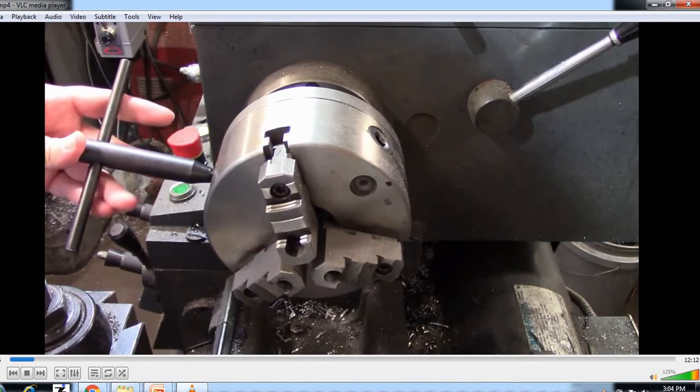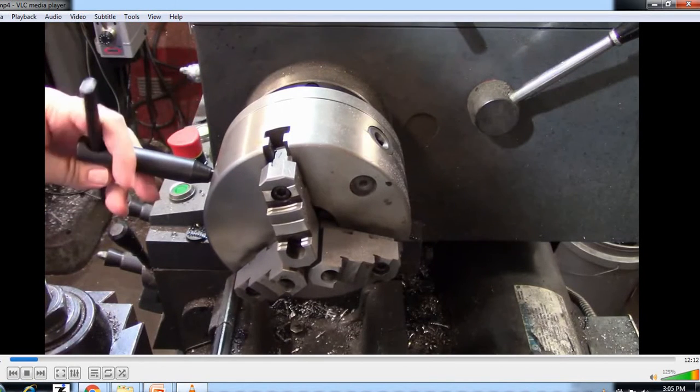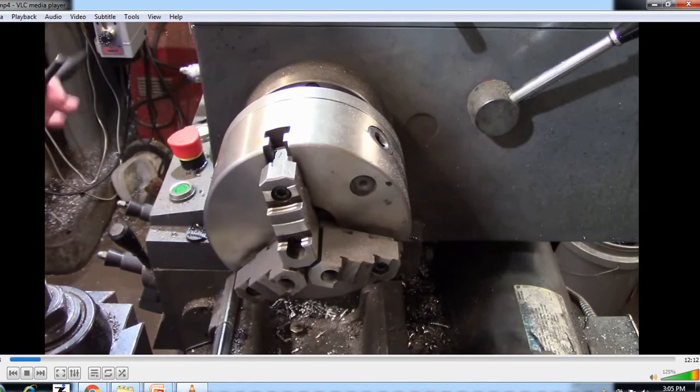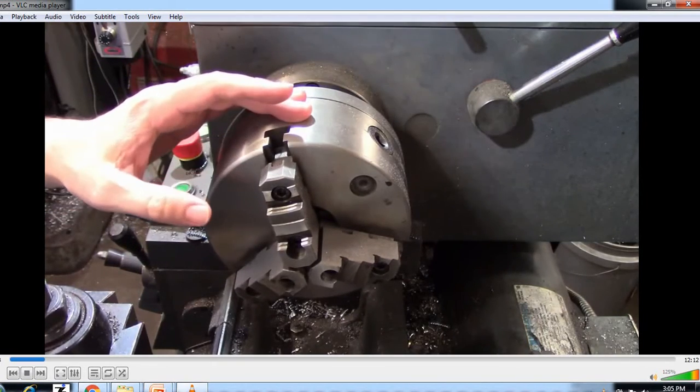Universal chucks are chucks where all the jaws move at the same time when the key is turned. They're excellent for being able to chuck a wide variety of diameters quickly. However, they will never clamp in the same place twice.